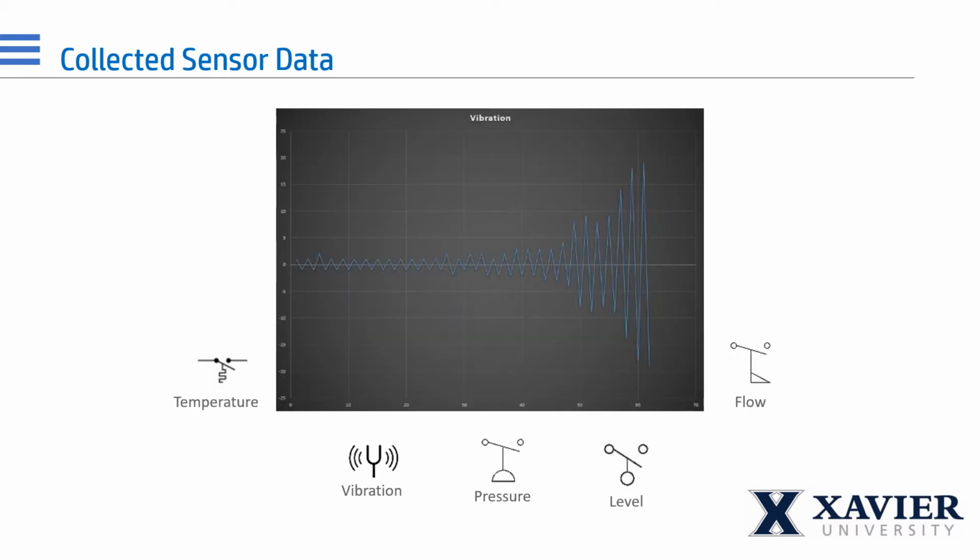Can we get an immediate benefit from this output? Yes, we can. Here's an example of that vibration signal. Let's say we see several weeks of uniform vibration, then all of a sudden something changes. Monitoring this type of output will allow us to see potential problems before we may be able to hear or feel them at the machine. This allows for a data-driven decision-making process.